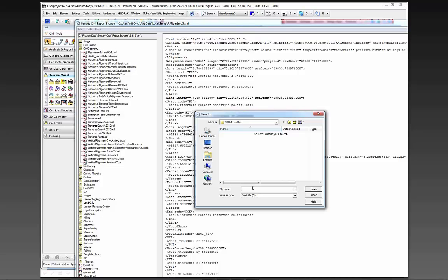In this case, this would be AMG, and I have already done it here, so I'll make a new one: AMG-alignment, and you can put State Road 61 or 61, however you decide to do it. I'll put State Road 61. Notice that I'm not changing the save as file type. This is important because if you click on this view, you're going to see an XML version of it, but this is for a web page XML, so it's been reformatted.